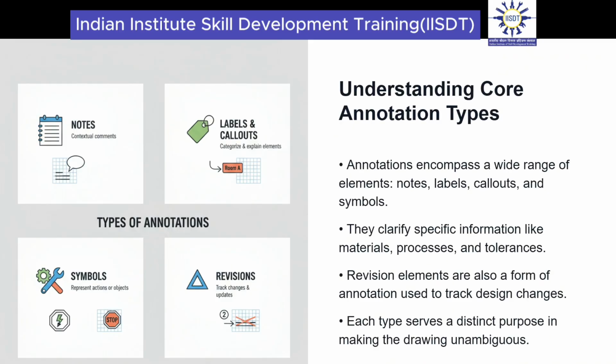It's a broad term that covers several distinct types of informational graphics. First, we have general notes. These often appear in a dedicated area of the drawing and provide overarching instructions such as break all sharp edges R0.5 max or all fillets and rounds R2 unless otherwise specified.